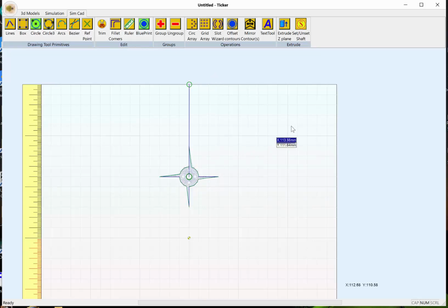So I'm going to draw another circle here, and I'm going to hang a pallet directly above that tooth pretty much. I'll hit my tab key and enter 5 millimeters for my shaft. Let's draw a larger circle to use as a boss. And let's draw a line from the center of our object all the way down. And this will be our release pallet. And I'll draw the line straight down at 90 degrees.